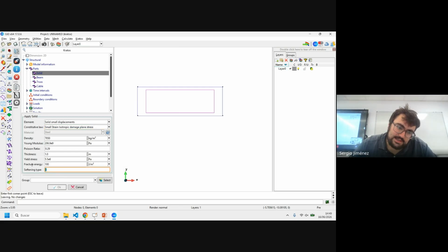The point is, if you want to use the by points curve, and you write number 3 here, nothing has changed. But in order to use this number 3 threshold function, you need to introduce new input information. Okay, this new input information cannot be added from the problem type, and this kind of information needs to be directly added in the material JSON file.